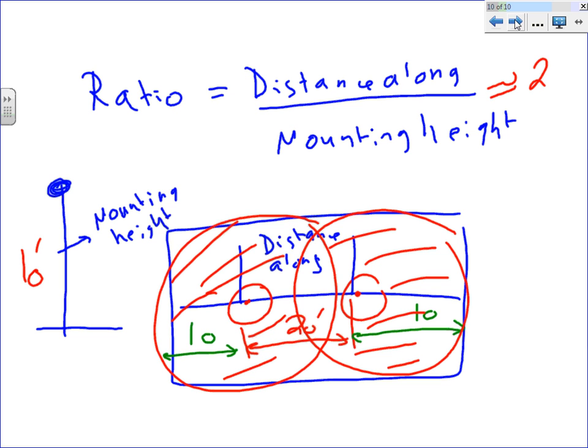Any questions, guys, my friends, about mounting fixtures? On page 47, guys, there's a couple of rules of thumb on how to mount 4-lamp fixtures. It says indoor situation, approximately one 4-lamp recessed 4-foot fluorescent luminaire per 75 square feet will provide 75 foot-candles. They're giving you an example.